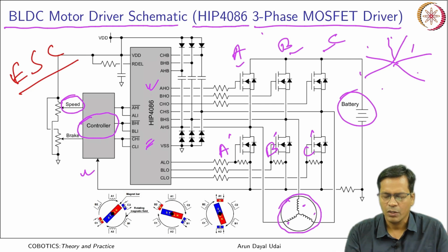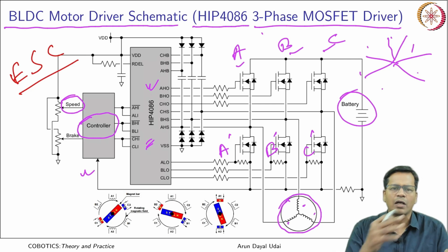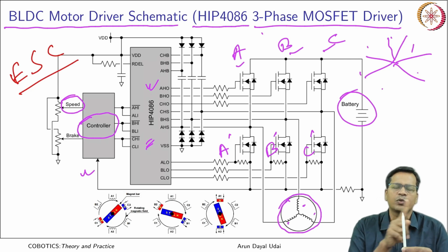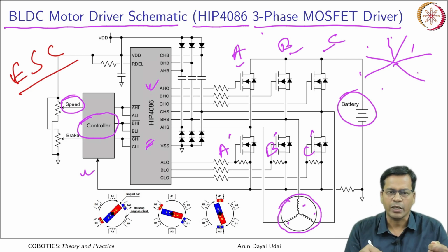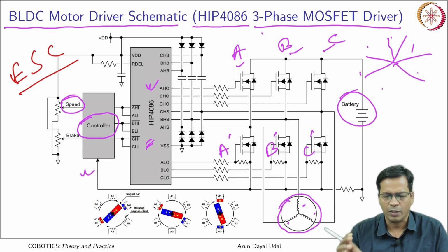But in case of cobots, you also need a Hall effect sensor. Where is your rotor? You need precise feedback before you switch on the next 2 coils. Accordingly it is made to run. It also has a precise angular feedback sensor which will give you precise angular control also.